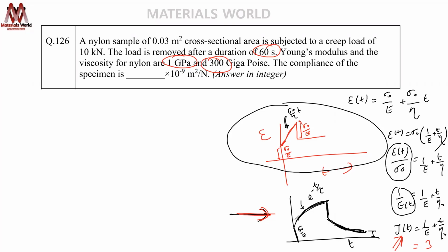The nearest one is Voigt, which tells you, I cannot tell you about the instantaneous deformation, but I can tell you about the retarded strain, and then the recovery. There is no instantaneous recovery also. So it ignores the instantaneous elastic strain that is going to recover. It only considers viscous retarded strain as well as retarded recovery.